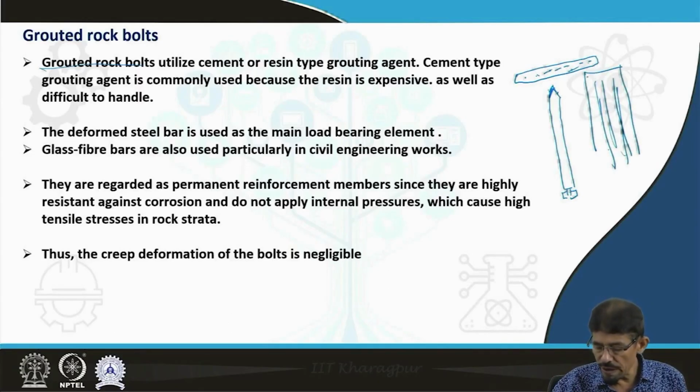Due to interaction between this wall and the surface, the tube lying at the top of the bolt is fractured, and the fluid cement material starts flowing and makes this bolt intact.